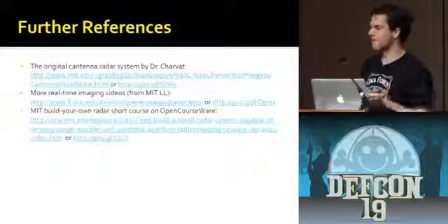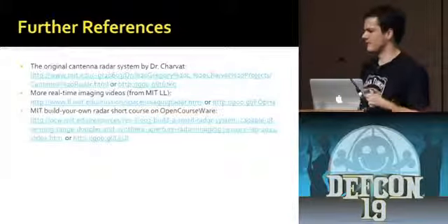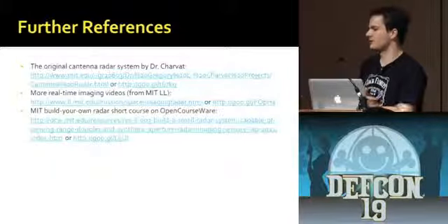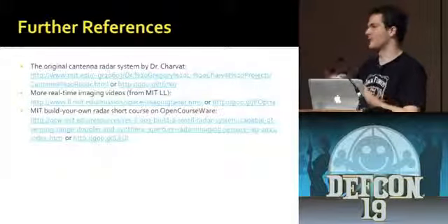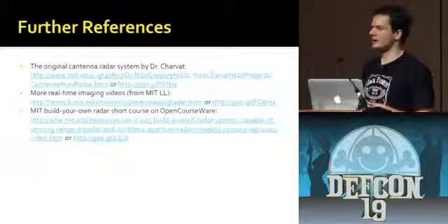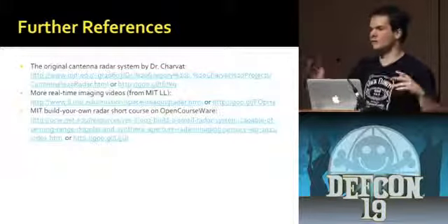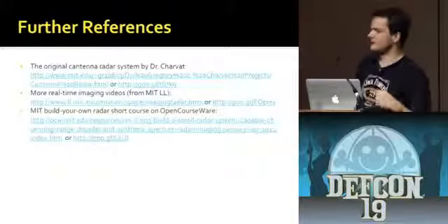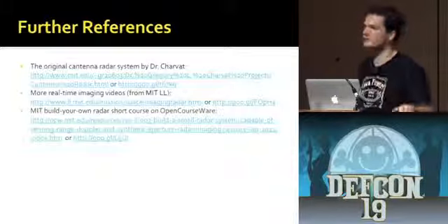So you could go up to 5 gigahertz. It would be a little harder to find parts. Basically, as you go up in frequency, the parts just get a little more expensive, or as you get even higher, they can get a lot more expensive. But the big thing you want in a system like this is wide bandwidth, because the bandwidth is what's giving you that spatial resolution and the time resolution.